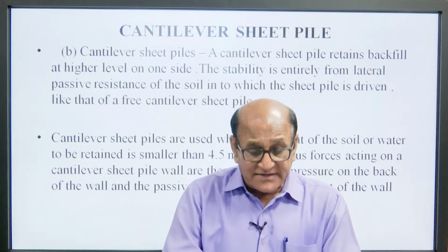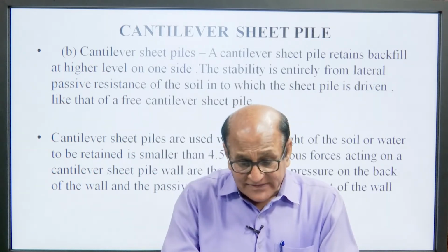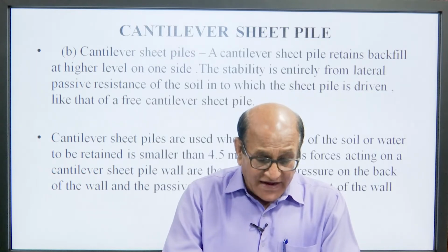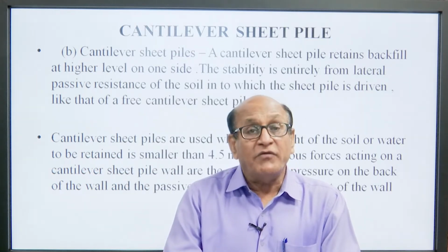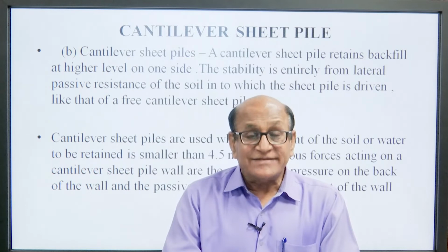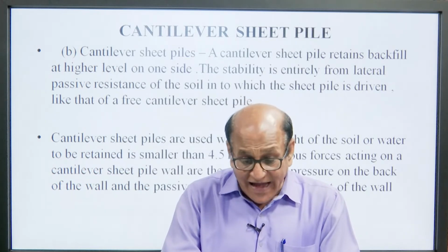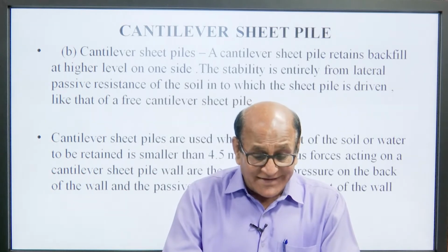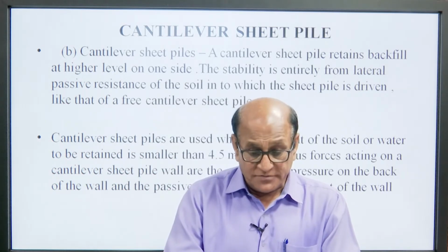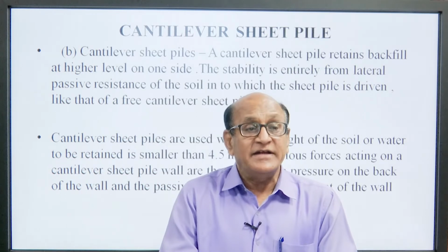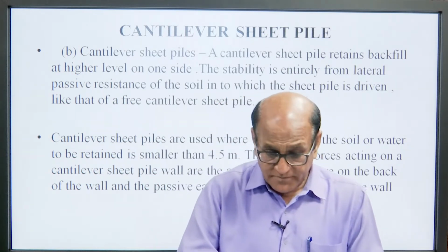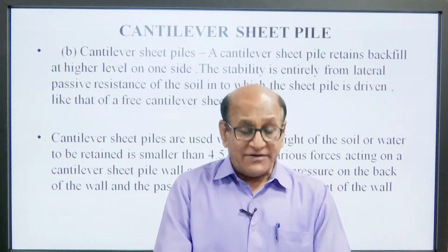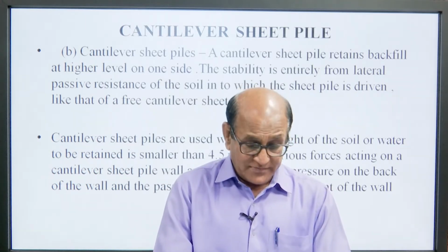Cantilever sheet piles. A cantilever sheet pile retains backfill at a higher level on one side. The stability is entirely from the lateral passive resistance of the soil into which the sheet is driven, like that of a free cantilever sheet pile.